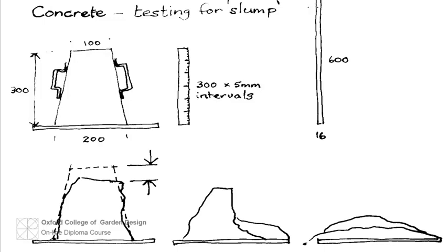Then use a 1 to 2 Portland cement to sharp concreting sand to make a cement-rich mortar in a batch mixer. This mix is pressed through the wire so that it surrounds the wire a minimum of 10 mm either side of the mesh. Aim for a 25 mm overall thickness of concrete. Make sure the whole pool is completed in one operation, otherwise there will be a line of weakness in the concrete.